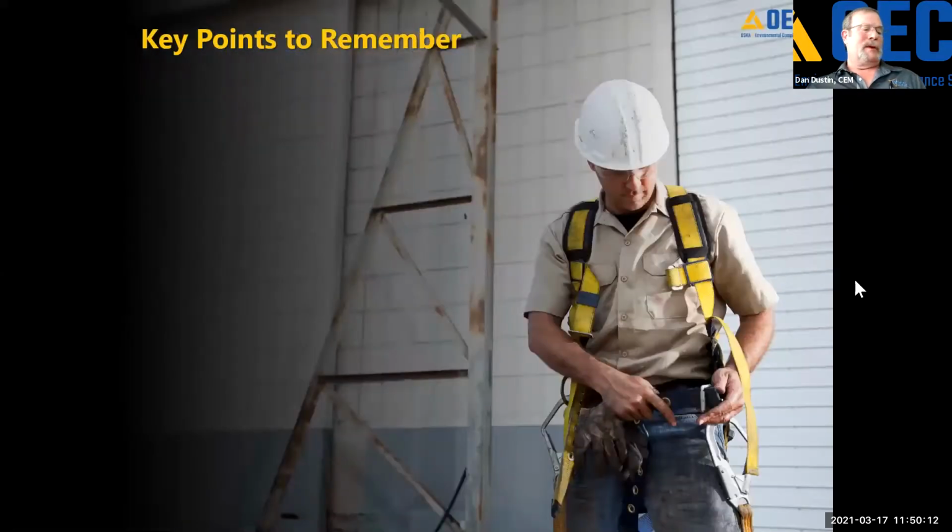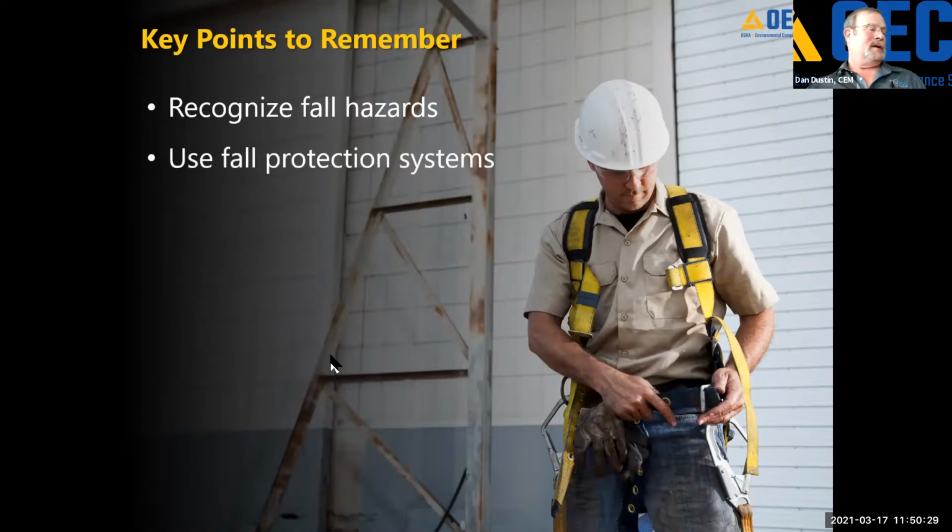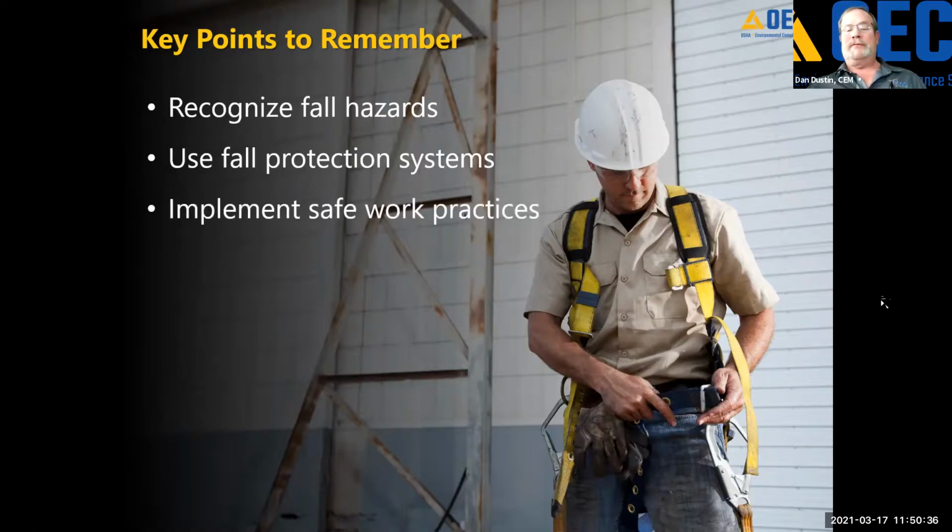All right, key points to remember from this presentation. First thing is recognize fall hazards. If you're not sure that what you're looking at is a fall hazard, ask somebody. Get a second opinion. If you're not comfortable with it, then assume that it is and treat it as though it is. Use fall protection systems, no matter which system you opt to use. Implement safe work practices. And part of that is making sure that people are trained that they have to put on a harness when that hazard exists, and it has to be worn correctly.